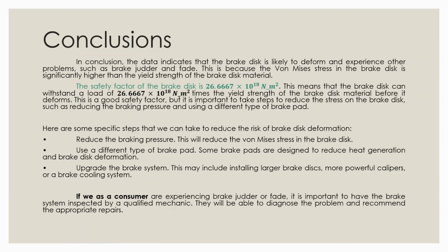In conclusion, the data indicate that the brake disc is likely to deform or experience other problems such as brake judder and fade. This is because von Mises stress in the brake disc is significantly higher than the yield strength of the brake disc material. The safety factor of the brake disc is 26.6667. This means the brake disc can withstand the load